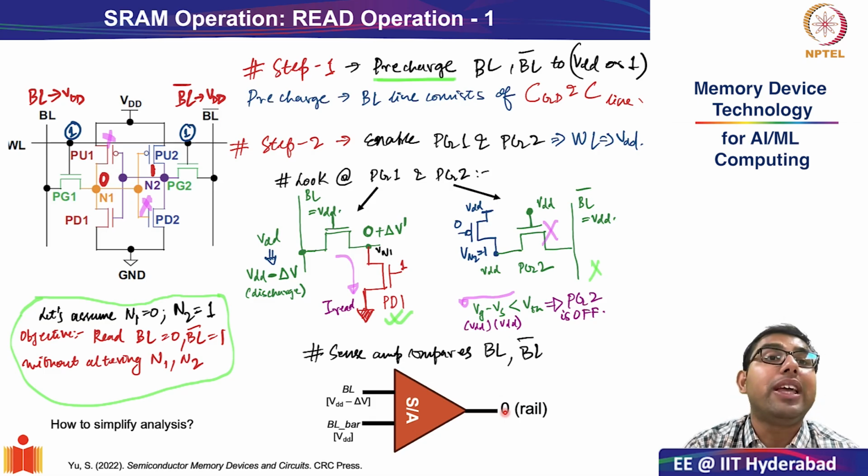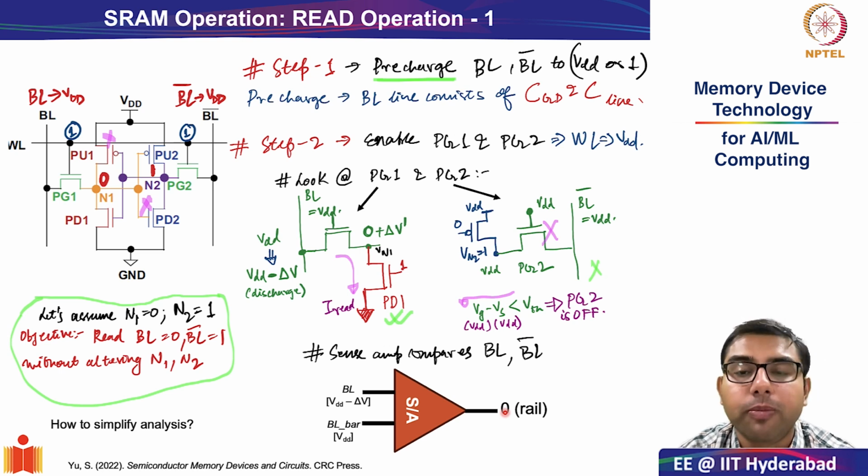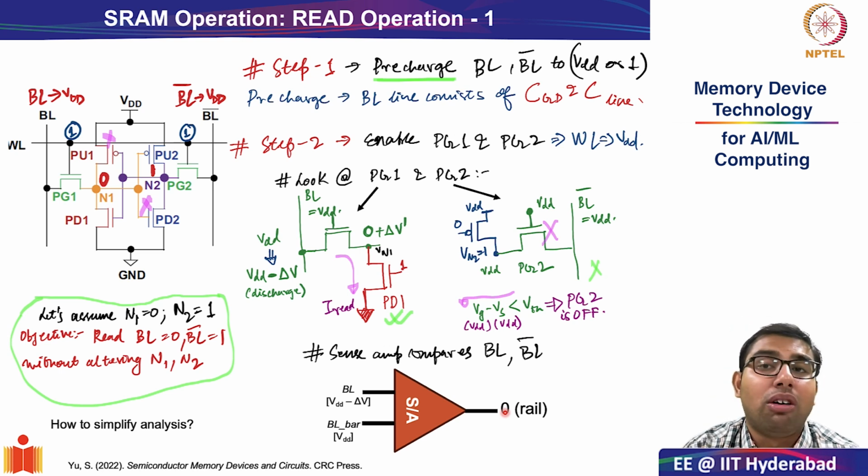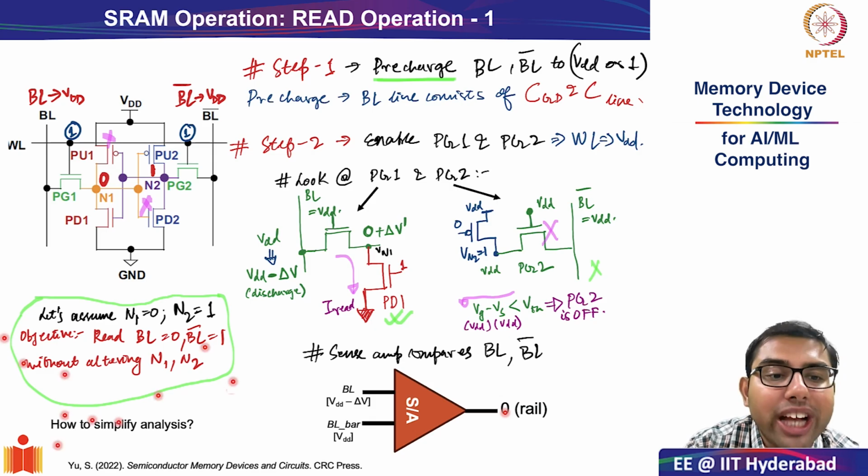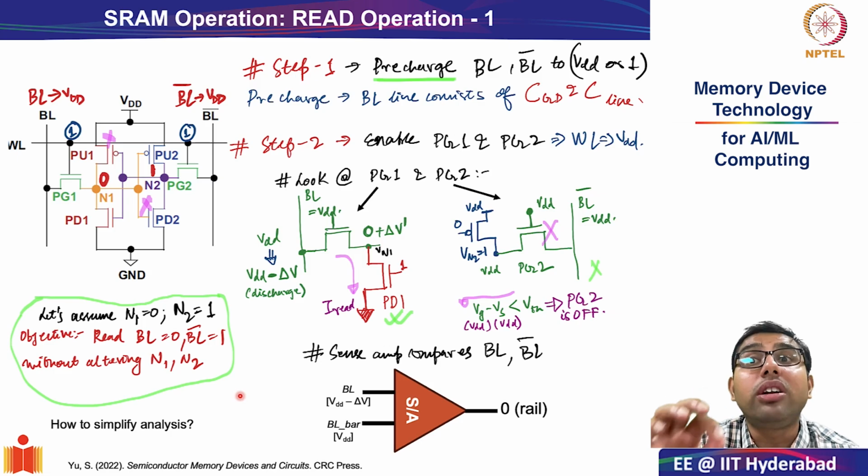So this is the entire concept of your SRAM read operation. However, all these things do not ensure one very important condition, and that is what we will discuss in the next slide, which is how do you ensure that all of this happens without the alteration of N1 and N2. That is a very important consideration.